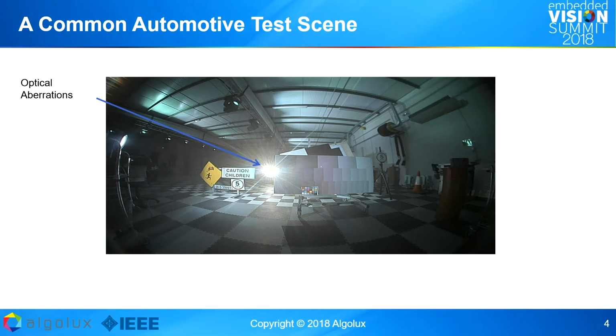You see the effect of headlights on the optics, introducing severe glare in this case, and spread of a point spread function because of the high illumination. What you can also see here, and this especially matters for rear view cameras, are optical geometric distortion and severe chromatic aberrations due to severe off-axis PSF spread.